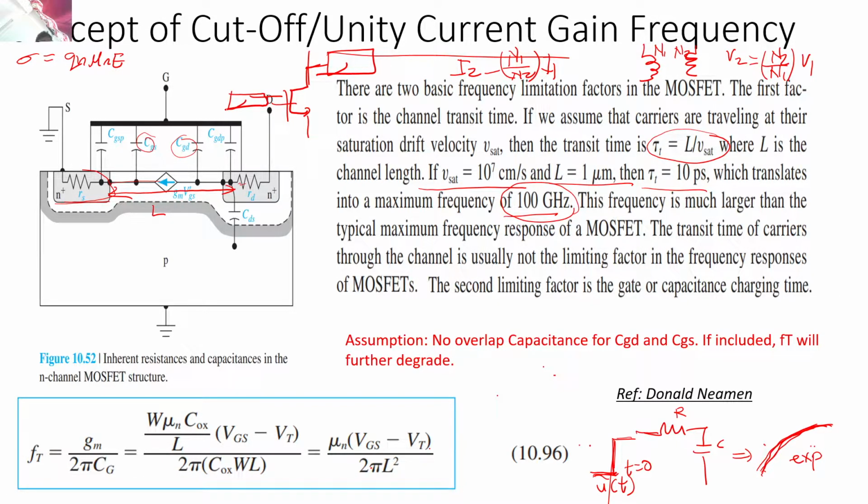But if you look at the current gain, first of all, why current gain? Because the biggest confusion is that no current flows through the gate of the MOSFET. This is what we had studied. There is an insulator present just below the gate metal layer. But if you keep on increasing the frequency, you have this CGS capacitance present over here.